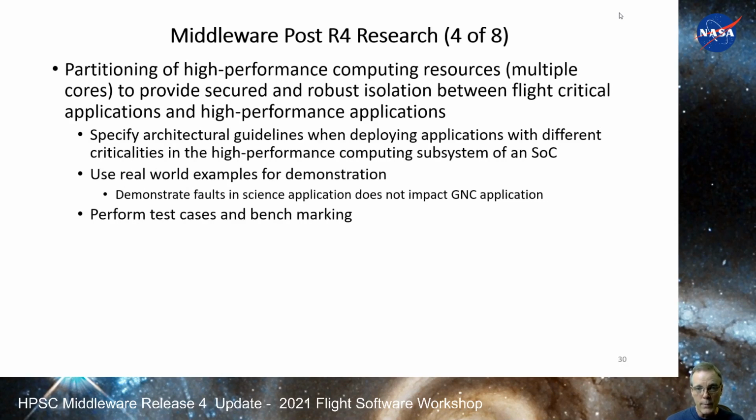Closely related to hypervisors and operating systems is the topic of investigating the partitioning of computing resources, especially when it comes to mixed criticality. We would like to experiment with hosting critical applications and less critical high-performance applications on the same SoC system and demonstrating the ability of the hypervisor to isolate faults between the two subsystems. This effort would include some benchmarking activities to help determine the overhead of hypervisors compared to a regular operating system.